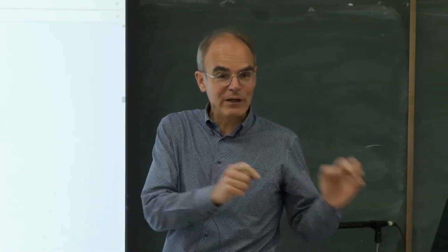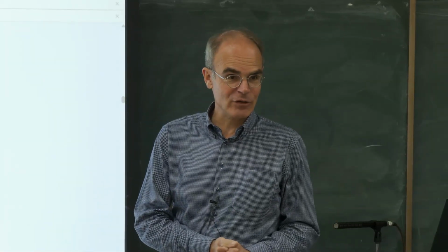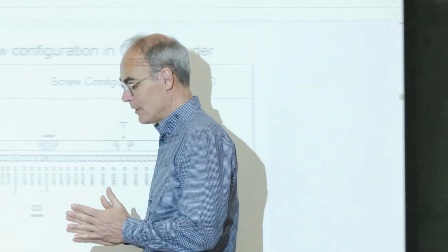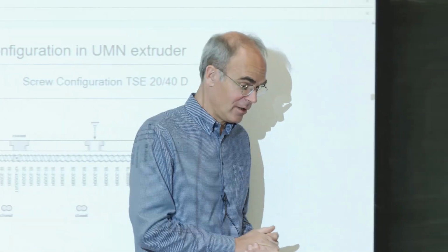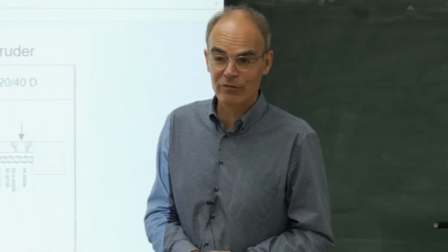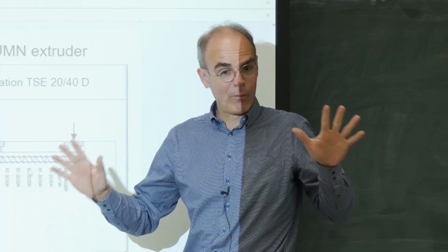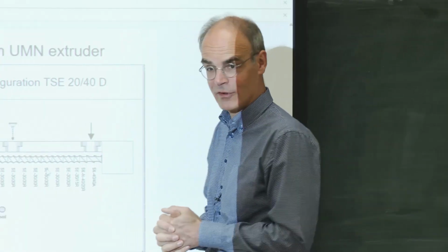Yeah, but you can reconfigure that exactly as you want, and really have special purposes. I recently did some recrystallization trials, co-crystallization trials in an extruder for a company. We had a completely different screw design for that because the whole purpose of the trial was different.